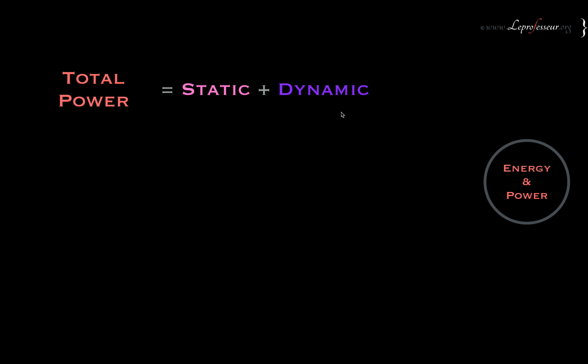And remember the equation of the dynamic power. The frequency term F comes in, and it is proportional to the square of the voltage. So voltage will have a very big impact on the dynamic power. That's why you might have heard the term: our chip was working at 1.5 volt, now it's 1 volt, now we are talking about 0.7 volt.